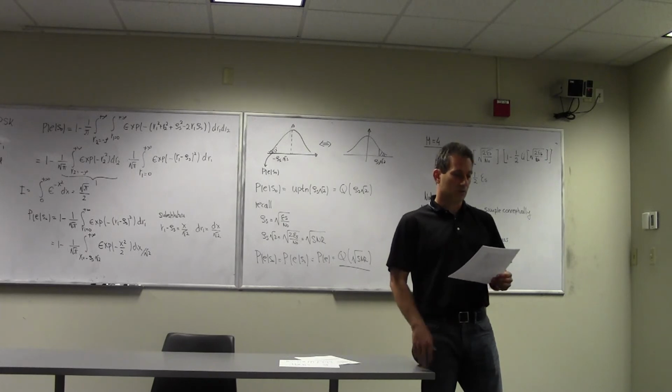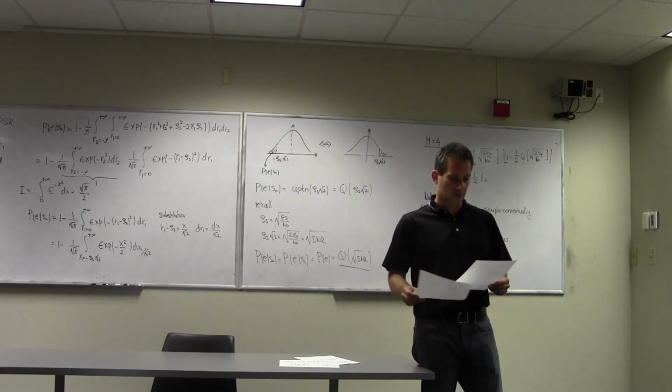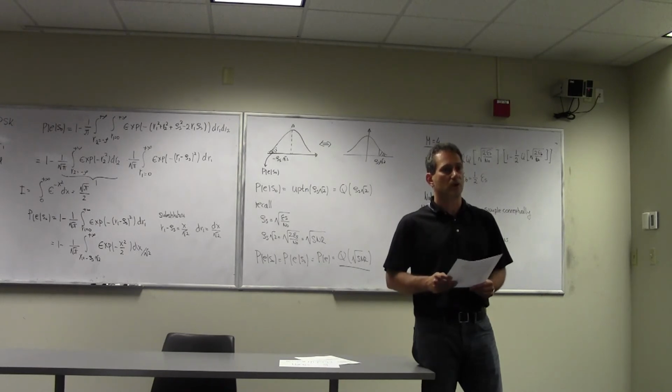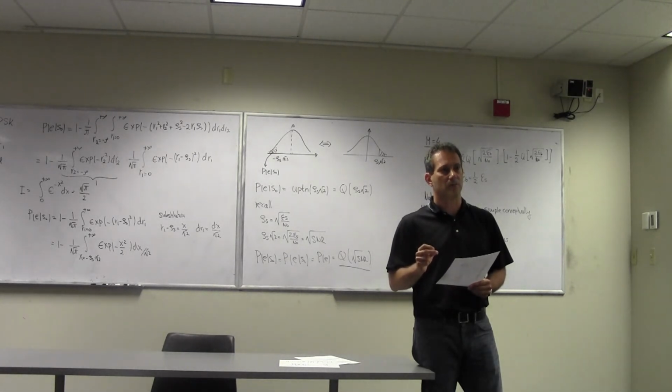Right? What you will notice here, and these curves show that clearly, is one of the behaviors that I taught before. And this is as your M increases, you then require progressively larger signal-to-noise ratio, or Eb/N0, to achieve the same probability of error.